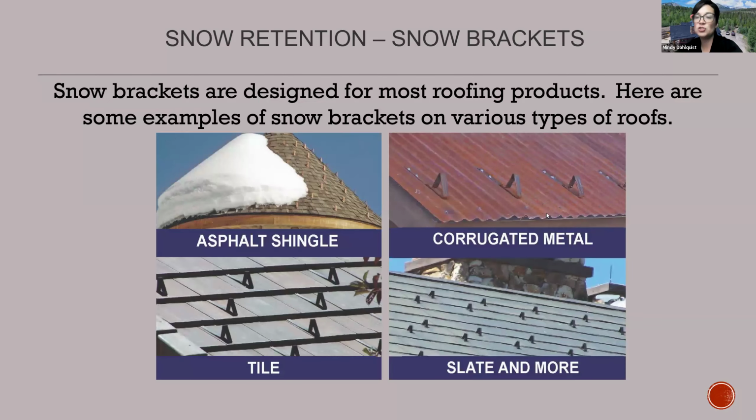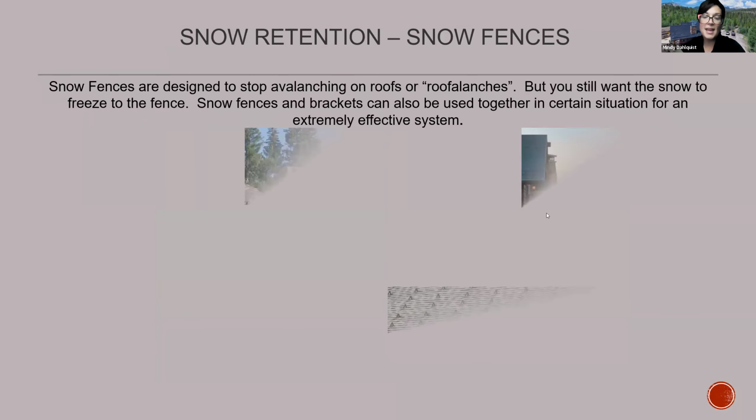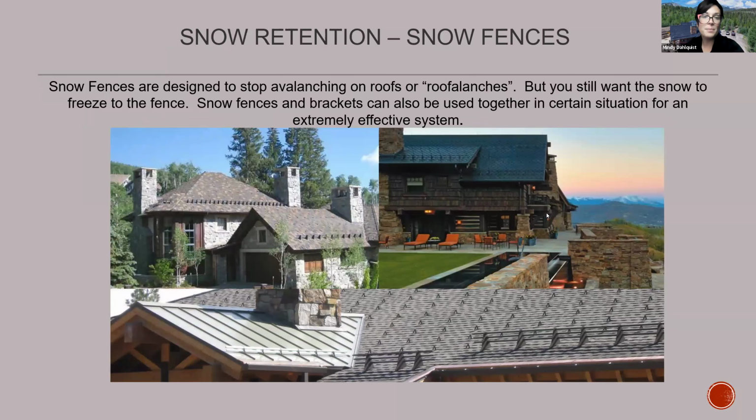They are a very strong product, but the reason they're installed across the roof's entire surface is because you are installing these with a certain type of fastener, and you can only be as strong as that fastener. So oftentimes many of them need to be placed across the entirety of the roof in a staggered pattern to hold that blanket up on the roof.